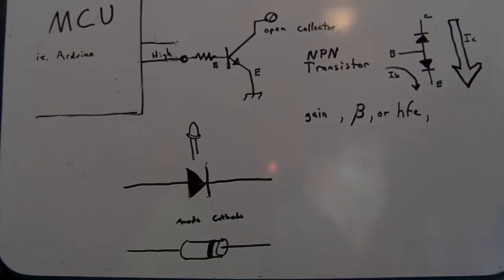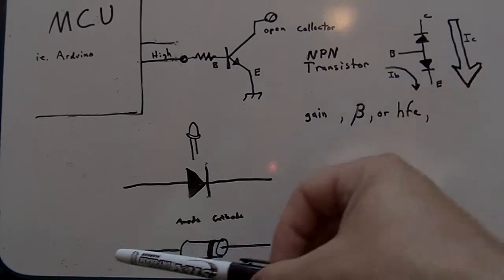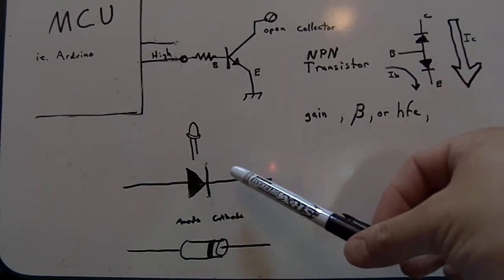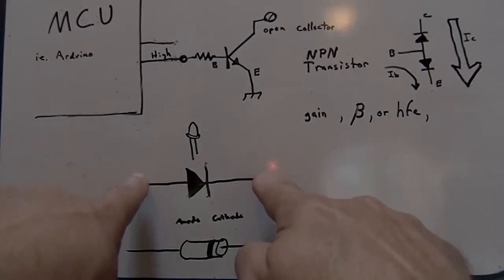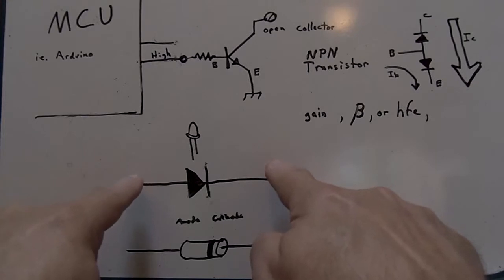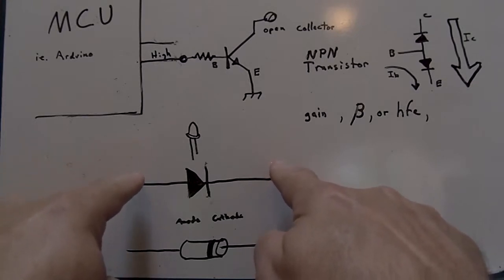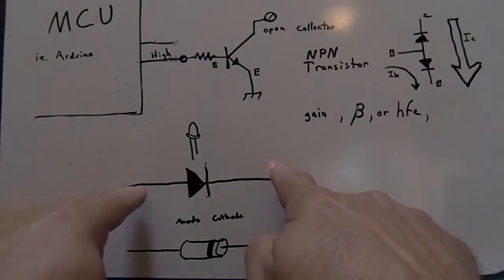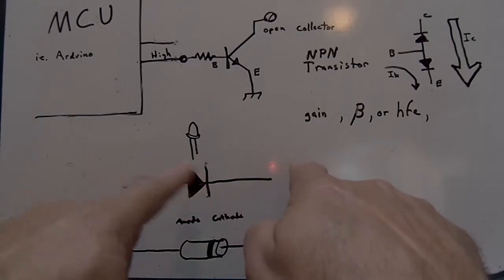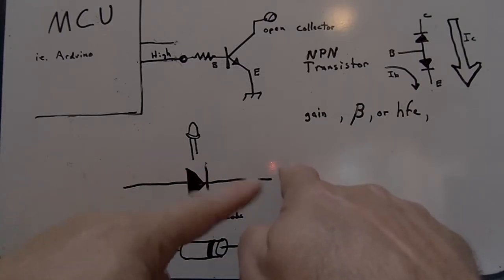Move on to a transistor. A transistor can actually be drawn as two diodes. So if I was going with an ohm meter, looking at a diode, I'd put my leads across it. My positive lead here, my negative lead here. Some Radio Shack meters actually have their ohm meter reversed, so you'd actually have to know that and mark your meter. That can really throw you off. But on most meters, the positive will be positive, because the resistance mode puts out a small battery voltage to test the diode with, or test the resistor with.